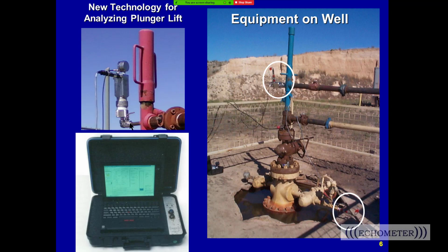Yeah. We have another question from Manuel. He's asking if there is no gas pressure to power the motor valve through the controller, what are the options? He's asking if a nitrogen cylinder, etc. What other options do we have? Yeah, you could probably pull the casing pressure or use a nitrogen cylinder. Those are 2 common methods.